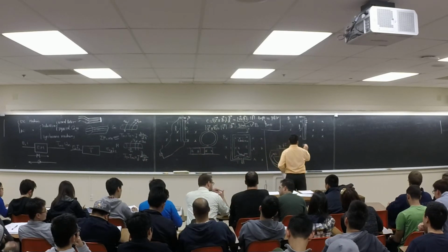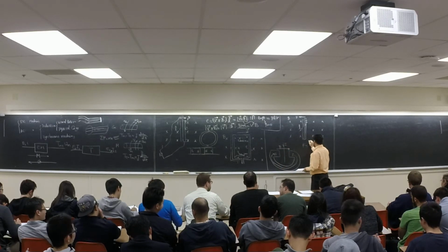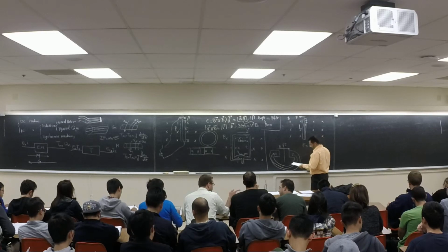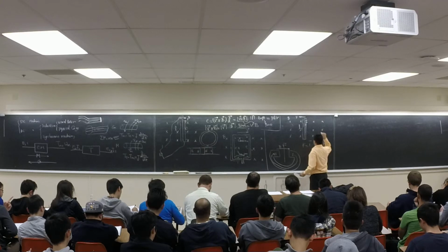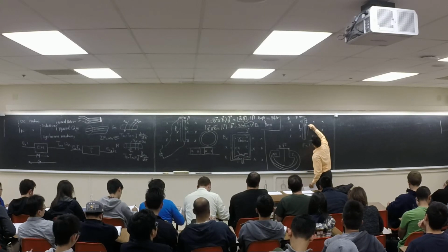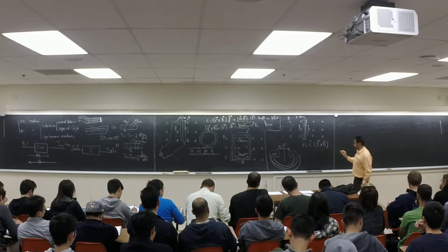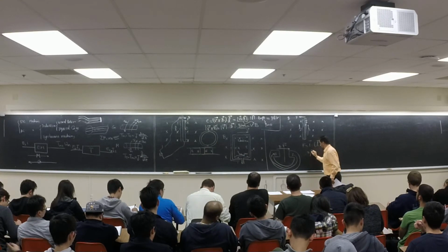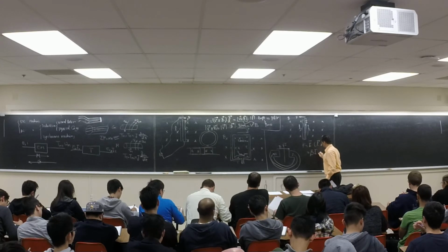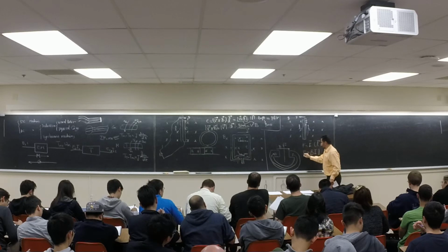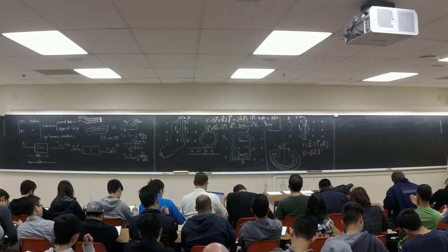F is equal to I times, again vector I, L, B. B is this one, L is the direction this way, and I is in the same direction as L. So if you simplify this in this case, it's going to be BIL. That's it. I'm going to use these two rules to get to the equation of the DC machine.